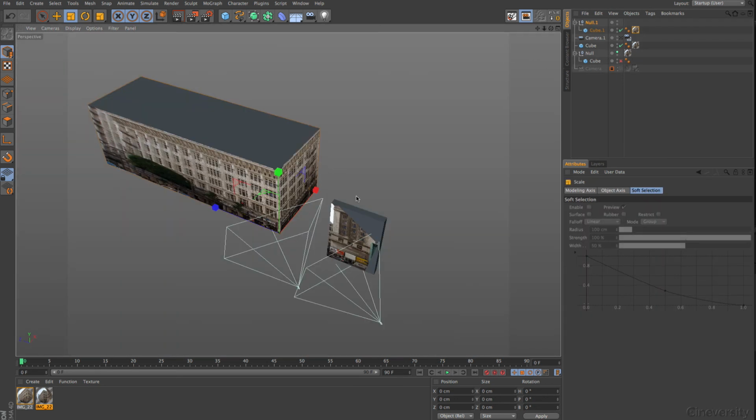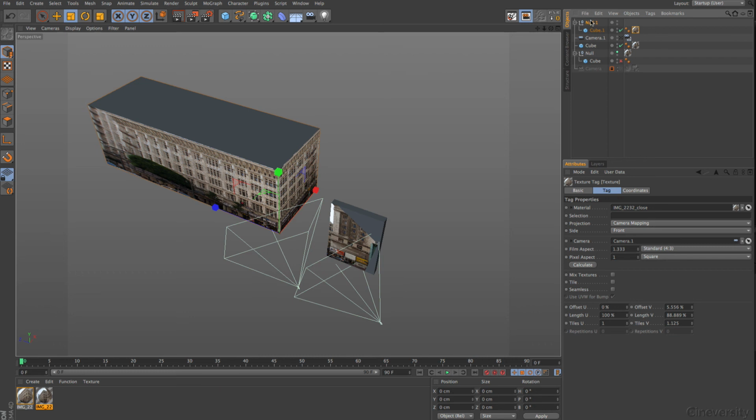When you want to move something, the geometry and the camera that is responsible for that projection needs to be under the same null object. And then you move the top parent with everything in it, not a single one left behind, because then the whole construction falls apart. So now you can place between these two cameras, with a little wiggle room of course, before and on the side, a nice camera path, as I've shown you at the start.